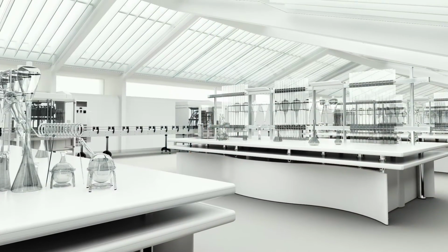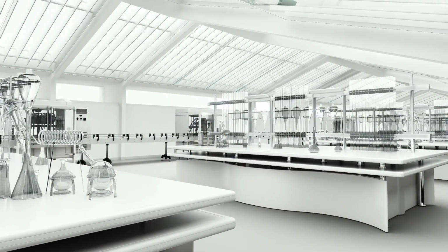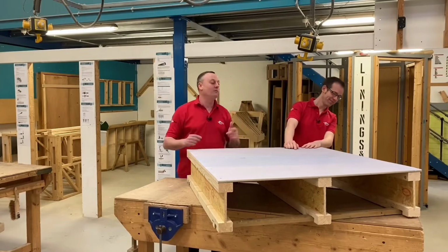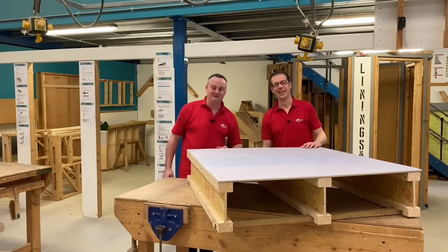On top of that, the way the space is used will also make a huge difference to the lighting level. A sterile laboratory used to prepare medicine will produce a lot less dust on the light fittings than a carpenter's workshop, and the former will be much more regularly cleaned than the latter. Also, the style of the fitting will impact on how dust accumulates on it, leading to further variance in lighting output. So how do we allow for the impact of all these variables?